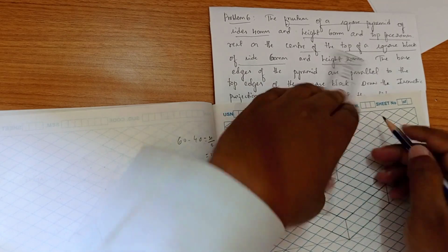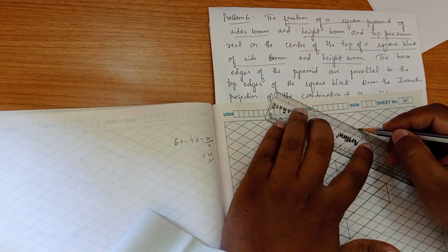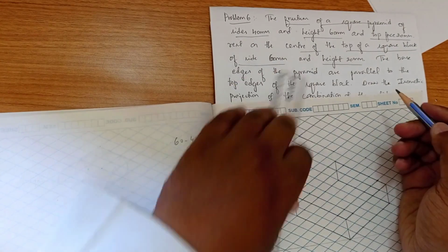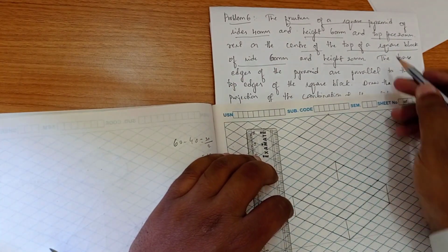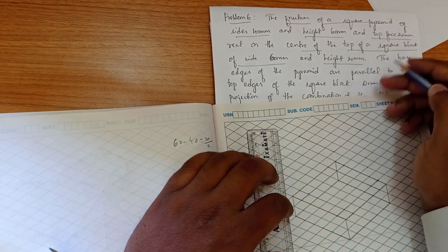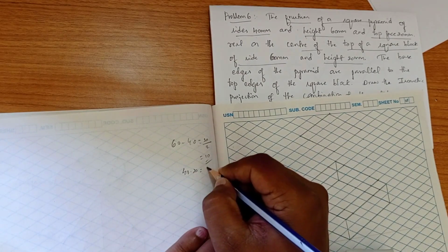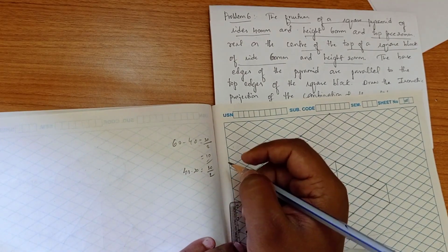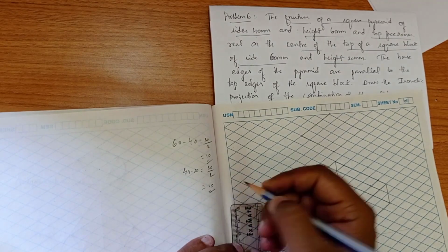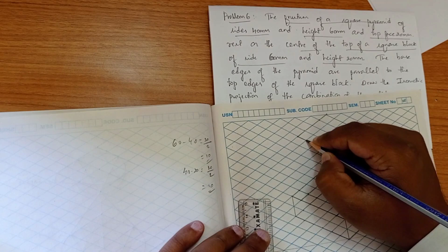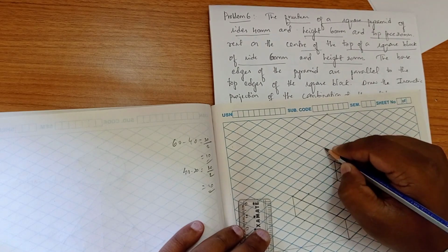So we have to construct a frustum here. You construct here a box of another 40, but at the top face we require a box of 20. It's again the subtraction of box method. So 40 minus 20 is 20, divided by 2 for either side, so we get 10.